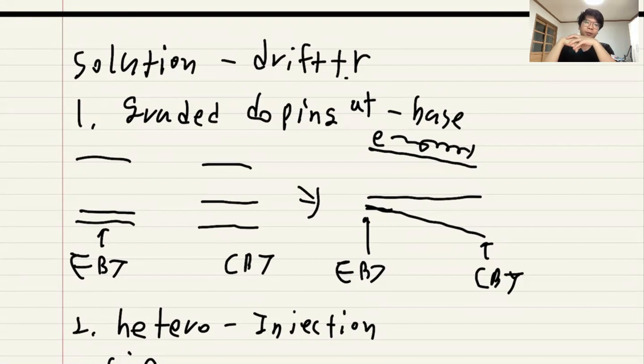By using this technique at active mode, electrons diffuse from the emitter to the base, and also diffuse through the base region, and by this potential difference, electrons get diffused to the collector faster. So the carrier lifetime would be shortened. The diffusion length and diffusion time get shortened, and there will be a low recombination current.